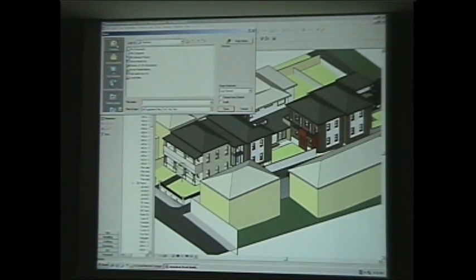But if you're going to create a large series of high-end renderings, you should take the model, develop it all in here, but then take it out into something like Max or one of the other rendering programs, because Revit's renderer is wonderful in its simplicity and in its connection with the model. I've built a model, I can turn around and hit render and get something without having done any work at all. And with a little bit of work, I get really quite a decent result. And as I modify that model, I can get instant updates, depending on the computer, to that model.